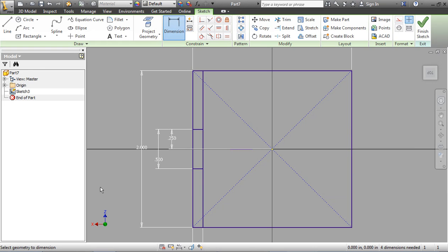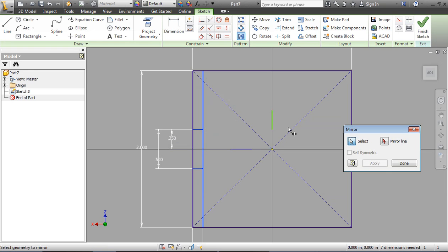Now, at this point in time, you have several different options. You can copy this to the other side, you can rotate it to the other side, you can mirror things to the other side. Multiple things all through here of rotate, copies, and mirrors. In this case what I'm going to do for this point in time is again create another mirror line and then highlight all these objects and then mirror them across this line.